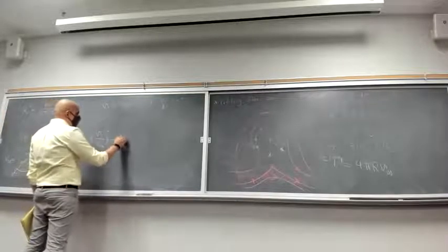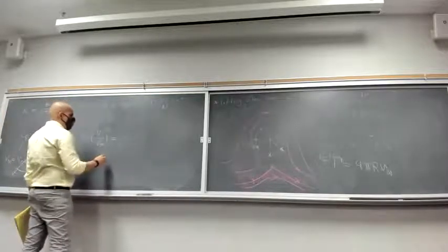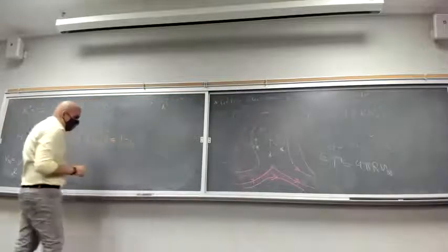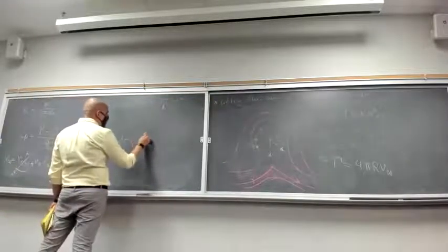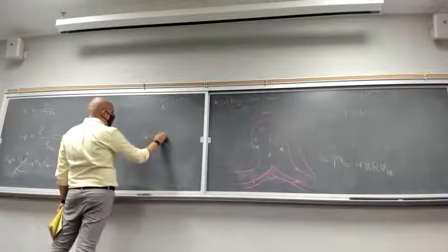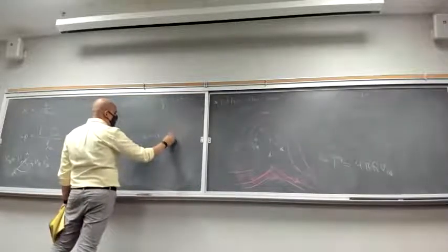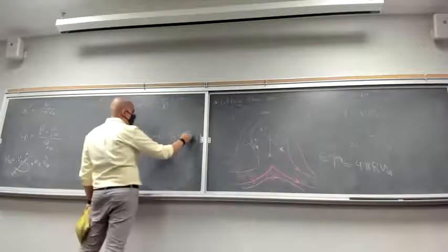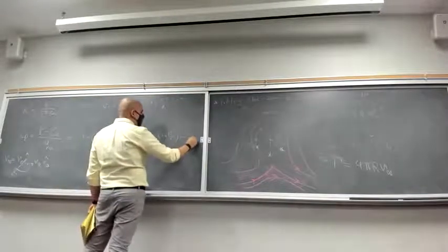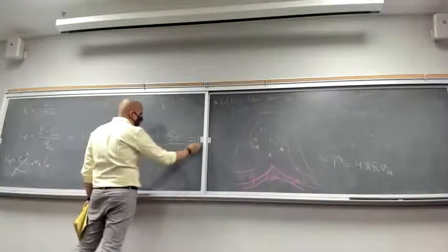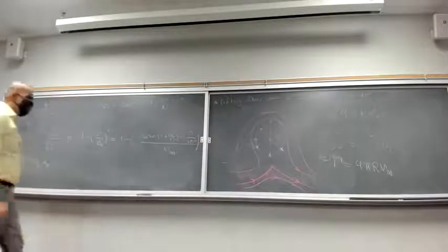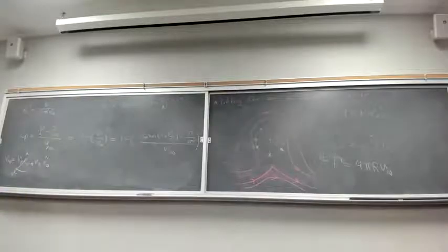So your pressure coefficient is going to be equal to 1 minus negative V infinity sine theta times 1 plus R squared over r squared, minus gamma over 2 pi R, divided by V infinity.